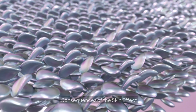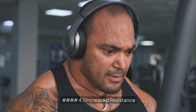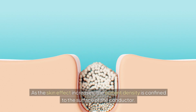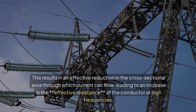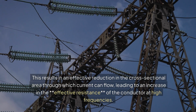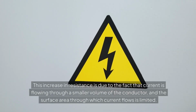Number 4. Consequences of the skin effect. Number 4.1 Increased resistance. As the skin effect increases, the current density is confined to the surface of the conductor. This results in an effective reduction in the cross-sectional area through which current can flow, leading to an increase in the effective resistance of the conductor at high frequencies.